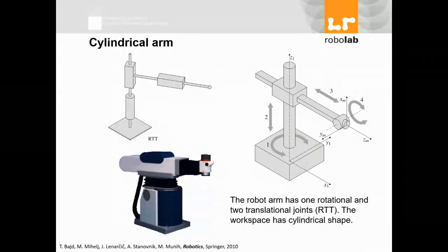In the cylindrical, I have to have a torque applied to this, force applied to this, and force applied to this. How you produce those torques or forces is really important. In some cases, one might be easier or more suitable than the other, depending on the weight, depending on the speed you're expecting, depending on many different things, just to make a decision between two types of robots which are more or less similar.